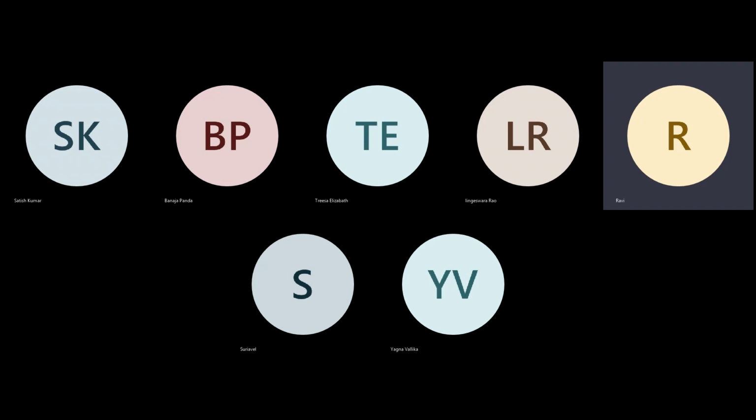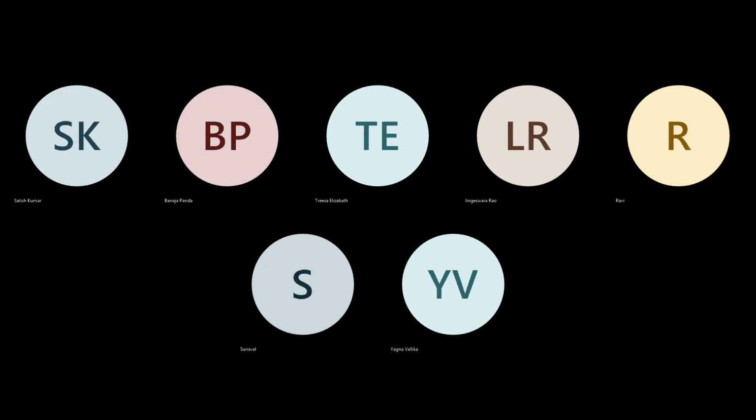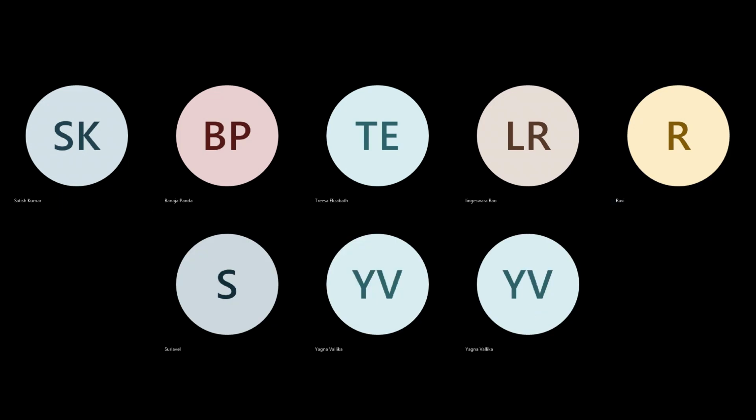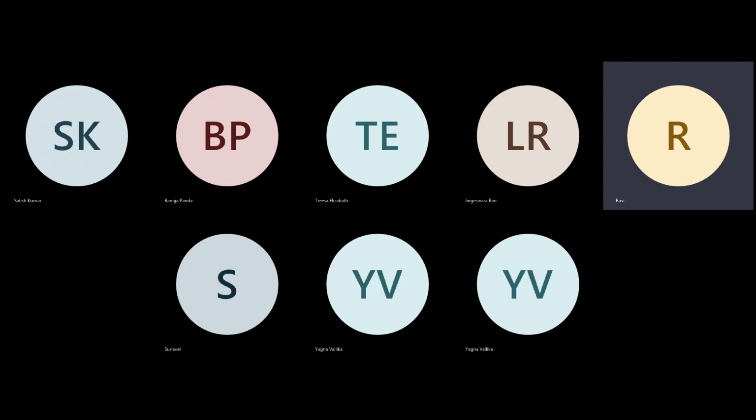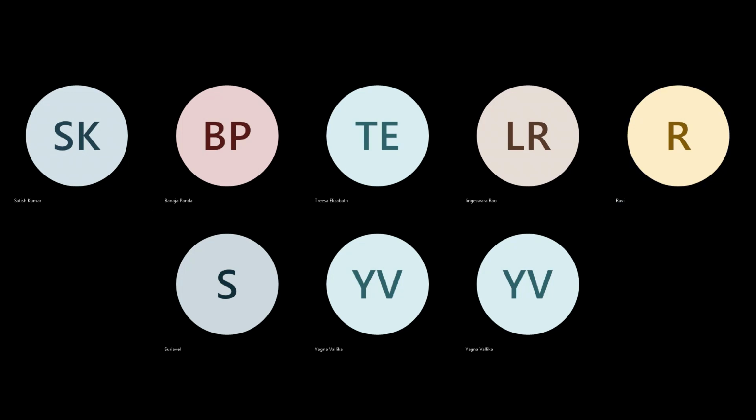So let's say 3 vertical layers are there. So 450 divided by 3, that is 150 each. 150 nets can be routed in each metal layer if it is 100% utilized. So you have to look at utilization, because if all the 150 nets are actually routed next to each other, crossed up, that's obvious, right?